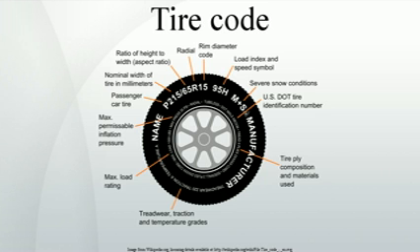Less commonly used in the USA and Europe, but often in Japan for example, is a notation that indicates the full tire diameter instead of the sidewall height. To take the same example, a 16-inch wheel would have a diameter of 406 mm. Adding twice the tire height, 2 × 107 mm, makes a total 620 mm tire diameter.